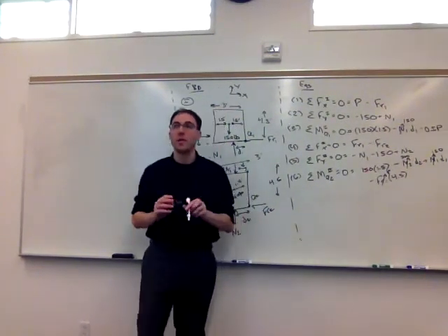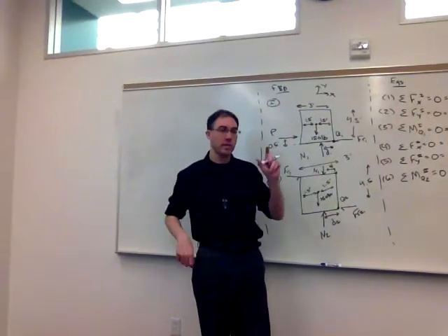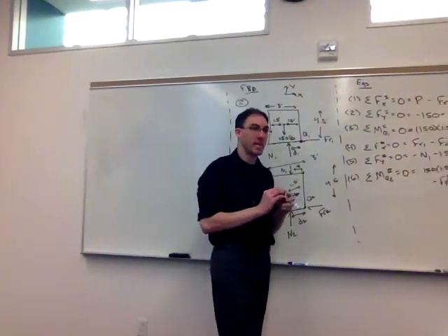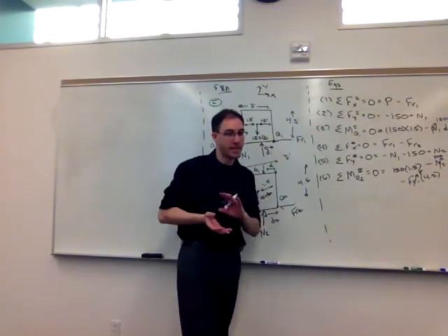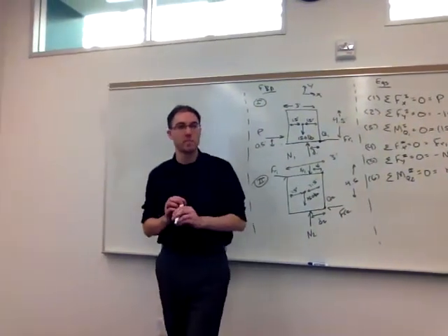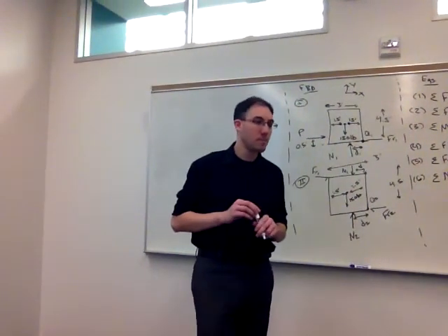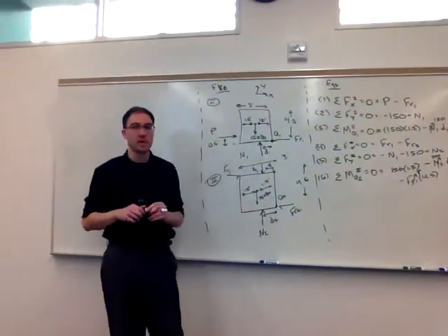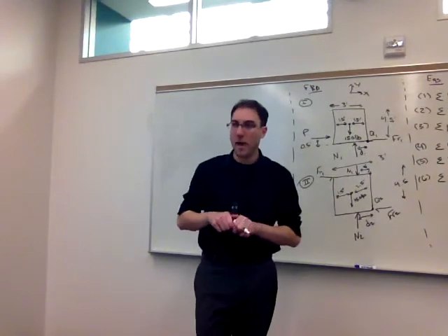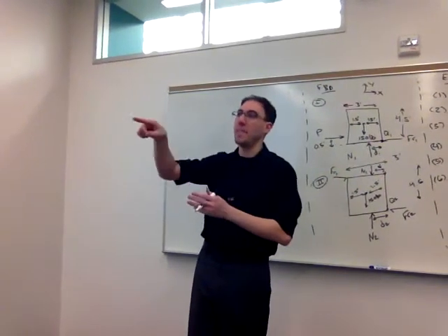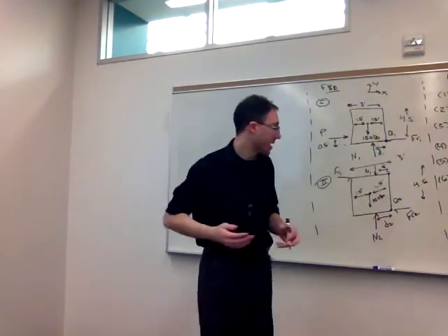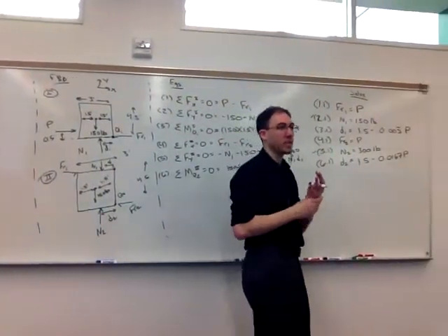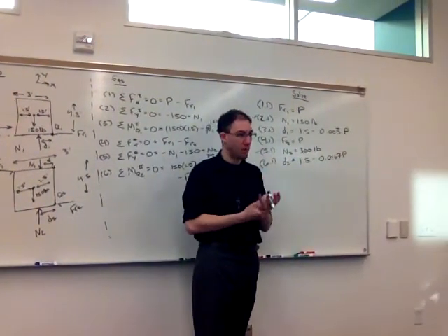It's a physical possibility, but in this case, because we're only looking at things on the verge of motion, that would not come into play. In a dynamics problem, yes, but in this we won't consider that. The bottom box stays stationary, the top box slides relative to it. And they both tip together? Right, they're stuck together and they tip at that bottom corner. They called it B, I called it Q2. So those are the 4 possible ways we could be on the verge of motion.